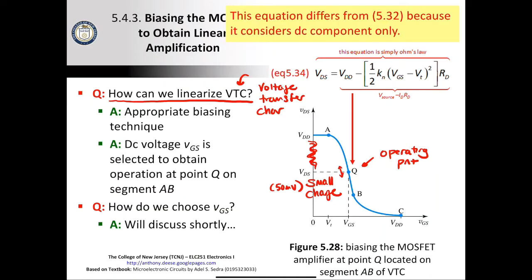But what we could do is, like we did with the small signal model, we could have a time varying component or a dynamic component, and we could also have a static component, right? Or a large signal and a small signal component. So if we take our 50 millivolt sine wave and then we add to it a DC offset of whatever the value is that we need, let's say 0.5 volts, then now our VGS, the small VGS, fluctuates around the linearization point.